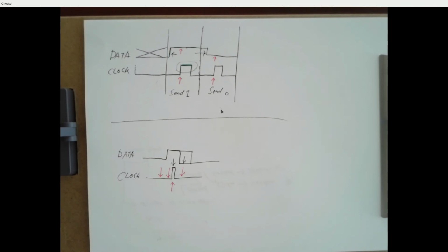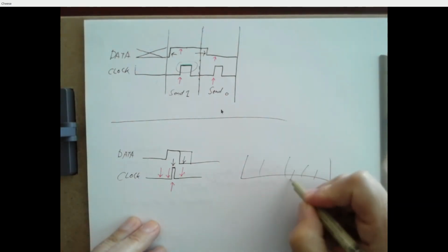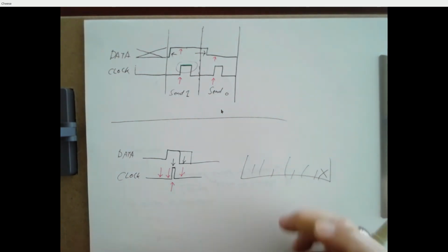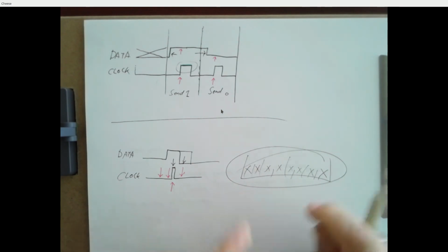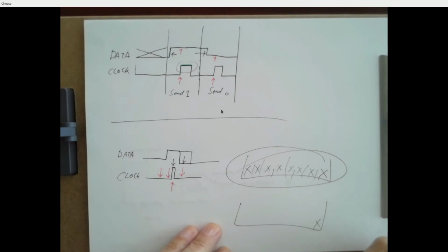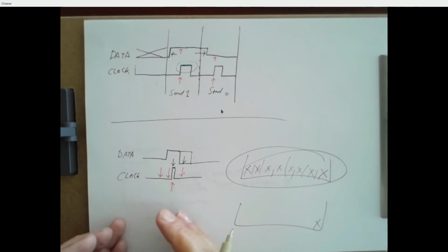Okay, so that's the first thing, transmission of a single bit, reception of a single bit. If you can do that, now you put your bits together to make words. So the protocol is characters get sent least significant bit first, total of 8 bits. So when you first run your receiver, wait for a bit, whatever bit you get, put that right here in bit 0 of some character. The next bit you get, put it in the next position, do that a total of 8 times until you've received 8 bits, treat that as a character. So print that out on your display or save it in a file or whatever it is that you're trying to do. The next bit that you get, the 9th bit, that's the least significant bit of your second character. And you just keep reading bits, and every time you've gotten 8 of them, you've received a new character. And typically just go ahead and print that out.